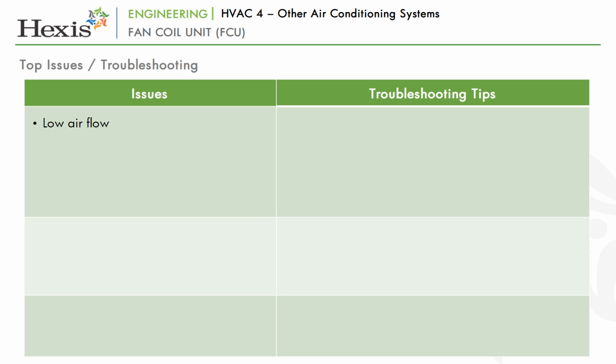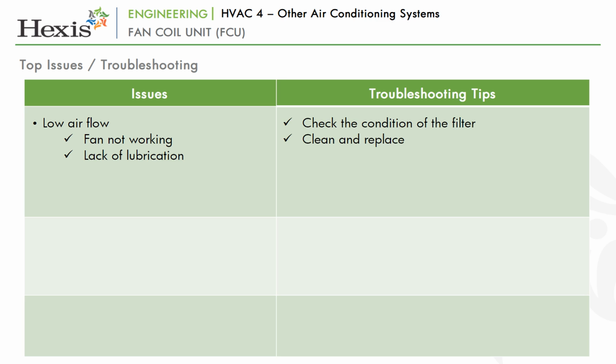Low airflow. The fan may not be working properly due to a faulty motor or lack of lubrication. If the fan is working, check the condition of the filter. Clean or replace as required. Thermostat faulty.